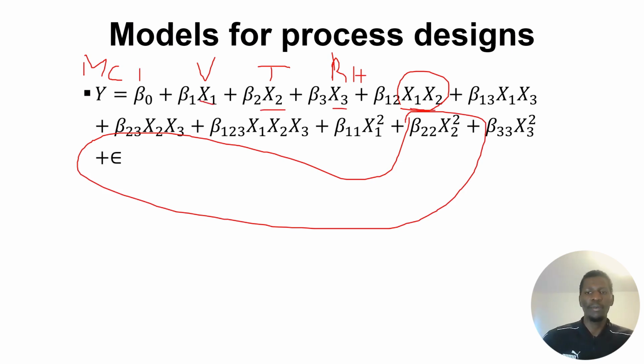When you develop this type of model, you see that you have 1, 2, 3, 4, 11 constants. To actually evaluate these constants, you need to develop an experimental design that has at least 11 runs before you can evaluate these constants and actually optimize the process.